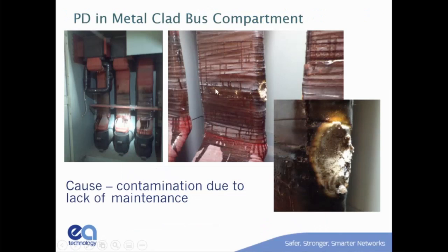This is a situation I was telling you about where they have bus bars, and they had this horizontal brace across the bus bars, and that horizontal brace was never cleaned. And it was in a swamp, in the Okefenokee swamp or whatever they've got out there. And it just had moisture and dust, and that created a path that made the field strength at the edges of this bus bar too great. And here's what happens. It just eats right into that insulation. This was screaming out ultrasonic. This you could hear with the naked ear. This was terrible, and it was on the verge of failure.